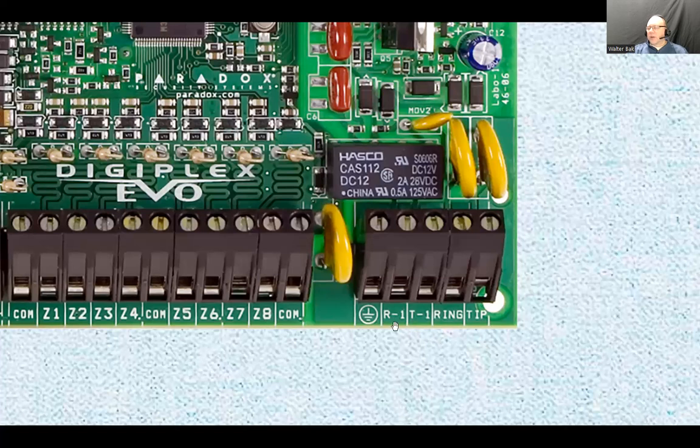And here's tip one. Does it mean you can connect two telephone lines? No. It means that if properly installed, this alarm system gets to have the phone line first. So if there is a phone line coming from the outside, it is wired straight into the alarm system first. And then out of that, the connection is carried on, and then the rest of the house gets the phone line. It has to go through this.